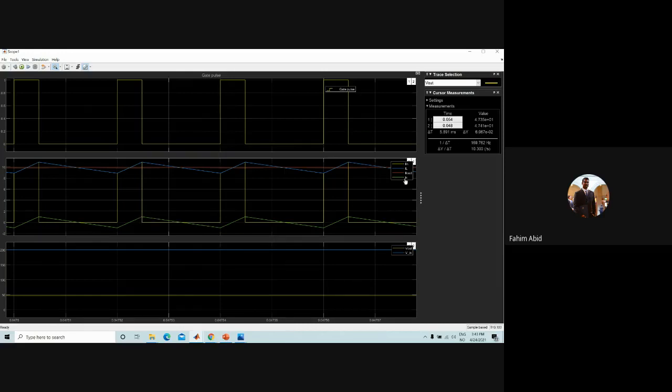And if you look at the capacitor current, it is basically the ripple part of the inductor current. It is exactly the same as the ripple part of the inductor current. Your load current IL is a fixed value. I haven't drawn the diode current here, but the diode current would be the same as the inductor current, only for the time when the switch is off.